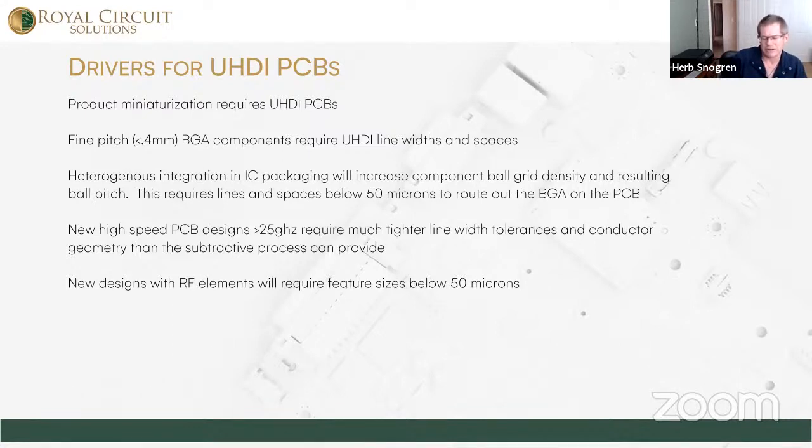And so it's the same size as the die. Whereas using an organic substrate, the substrate is bigger than the die, and so it's a separate component. So the die is actually placed on the substrate, whereas with chip scale packaging, the fan-out circuitry or fan-in is built up on the die itself.